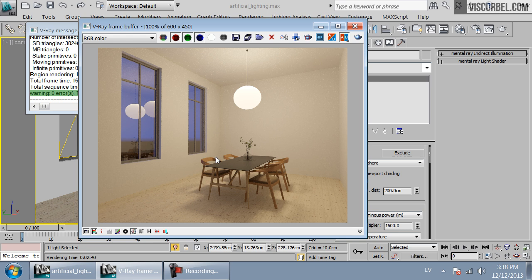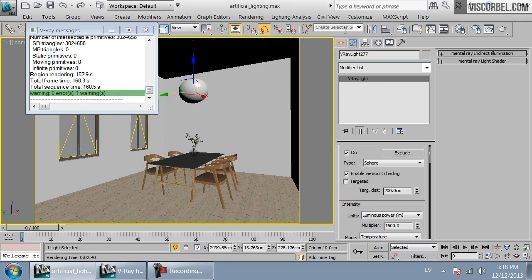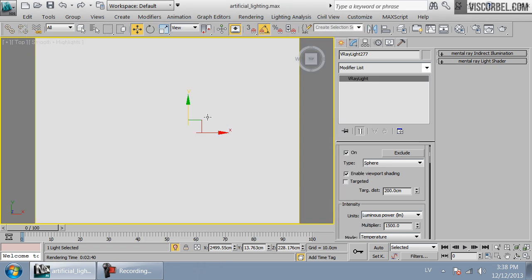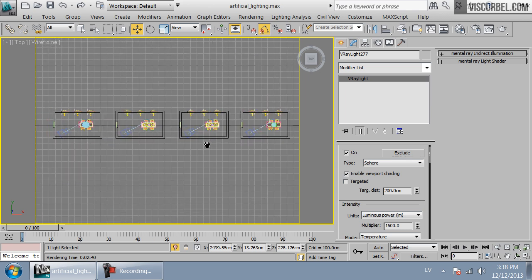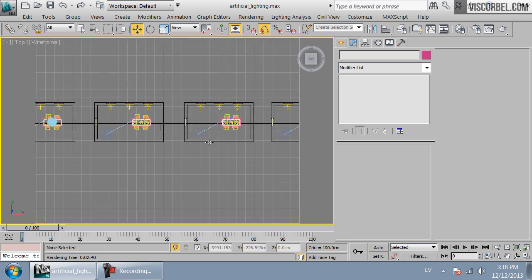So this is a good way to speed up your renders and still get a realistic result. So this works the best if you have a completely enclosed bulb. So there are no spots that should be brighter and no spots where you have this direct light. Everything is illuminated by this diffuse large enclosure. Okay, so the V-Ray two-sided material can be used in some other scenarios as well to quickly render the lampshades, especially if the lampshade is made from cloth or paper.